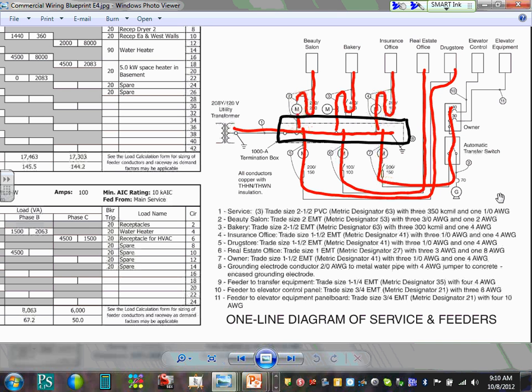Because multiple tenants, you come to a gutter, and from the gutter, everybody knows what a gutter is, a box with the cables in it. And from there, if this is big, this could be a gutter here up to 30 feet. You bring the cables in, you tap from the cables, and you go to the meter and disconnect. Can I have thumbs up, Chad? We fully understand that? Cool. So that's what this system is.